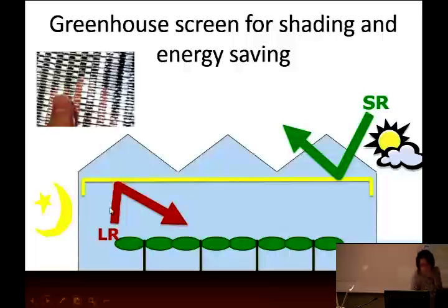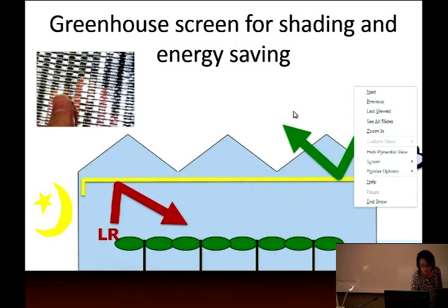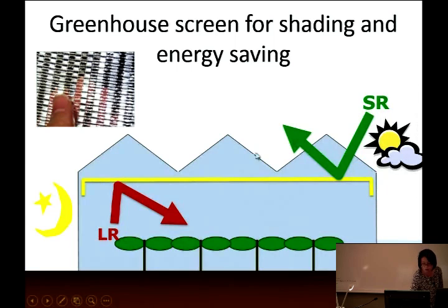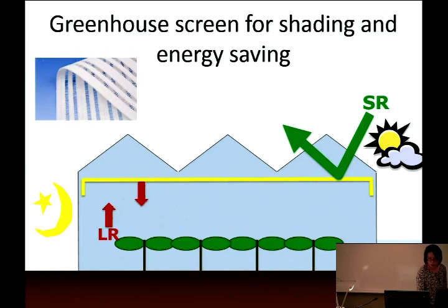So this is an internal curtain used in the daytime as a shade cloth, and during the nighttime reflects back and retains the energy when temperature is low, okay? Another material may be a different type of plastic, and it's also shade cloth. Having that layer would create a warmer surface compared to the glazing surface. When outside temperature is very, very cold, the glazing surface is also cold.